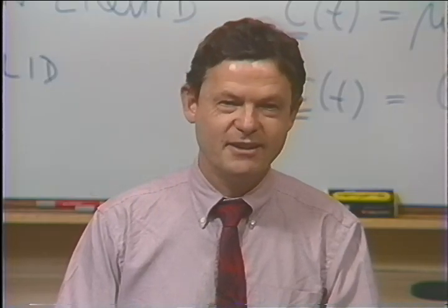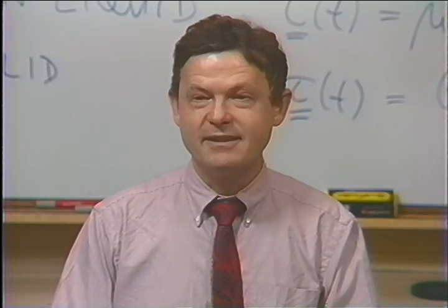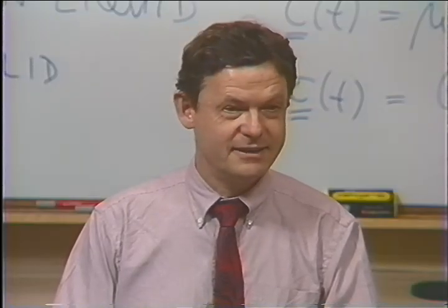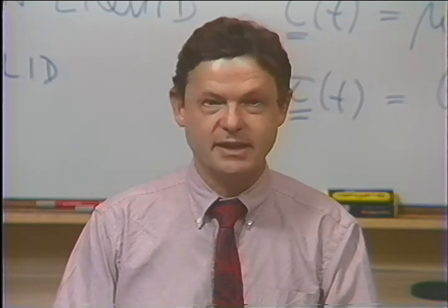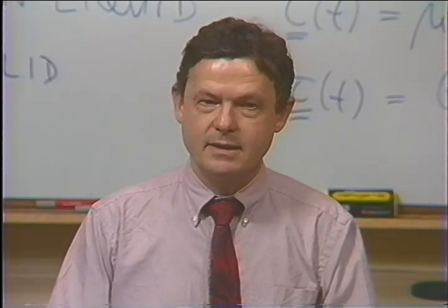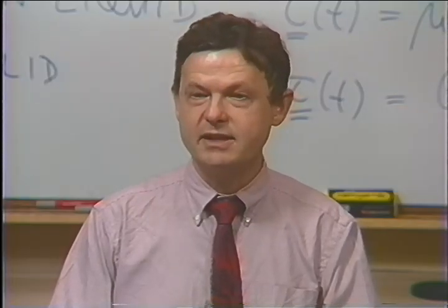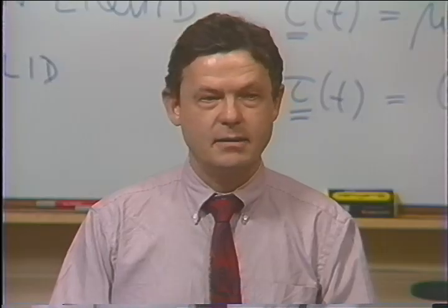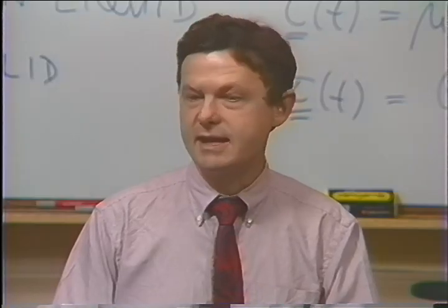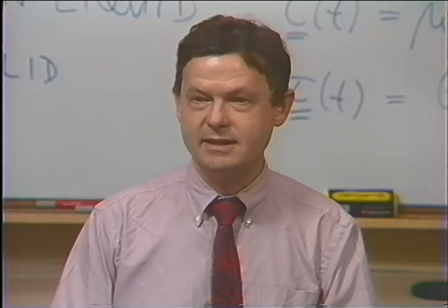And there's only one equation which really makes it easy. The jungle of constitutive equations starts with large strain behavior. The question is, how can you describe large deformations in shear and extension and all of this? So in linear viscoelasticity, from a phenomenological point, you have one equation. But we still would like to know which molecular motion, or what model for the molecular motion, gives the right value for the relaxation modulus. And that's where the different opinions come up in linear viscoelasticity.